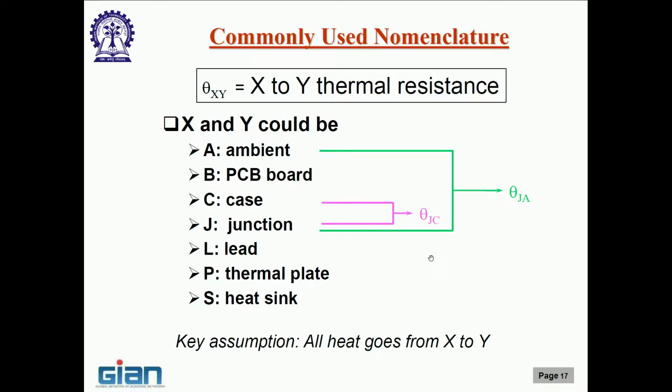All right. If not, let us go to thermal resistance for packages. Okay. We will start with a few nomenclature here, and then try to look at them in more depth. The thermal resistance is often denoted by theta. Okay. So, theta x y, which is the thermal resistance from x to y. Okay. Now, what is x to y? What, in the context of an electronic package, is an x, what is a y?